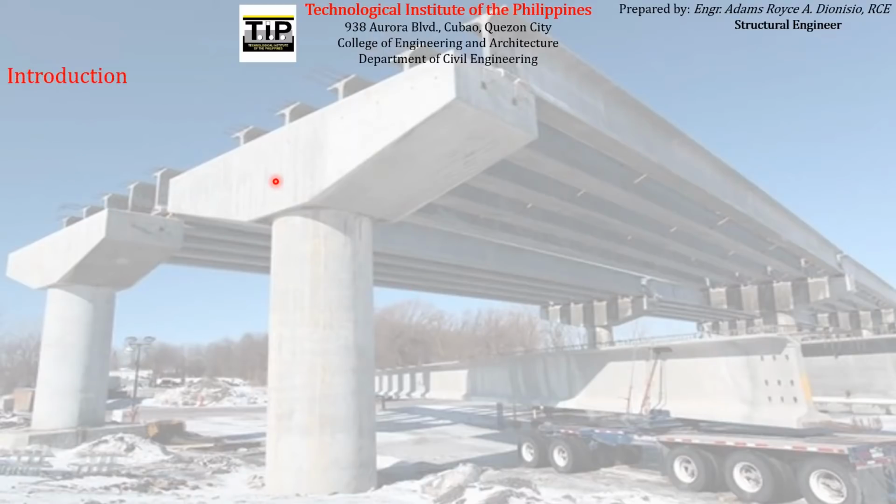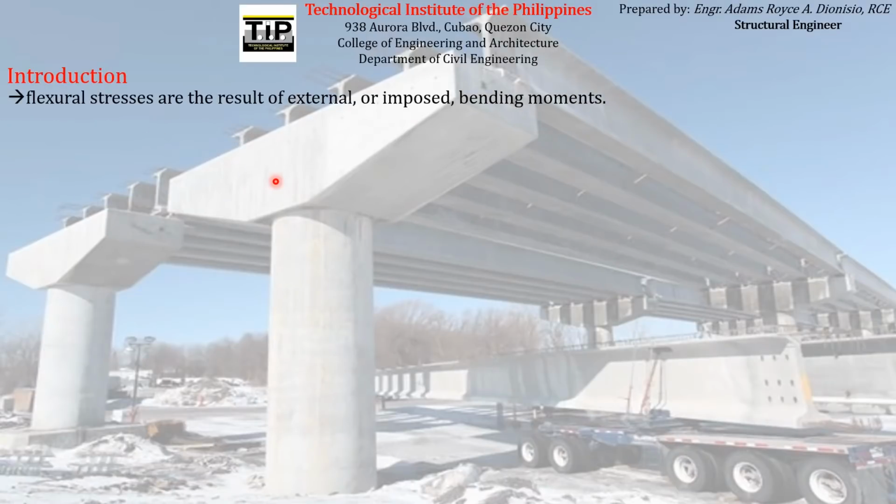So just to give you an introduction about the flexural design of prestressed concrete elements and why we are doing those design. So for our refresher, we know for a fact that the flexural stresses are the result of external or imposed bending moments.